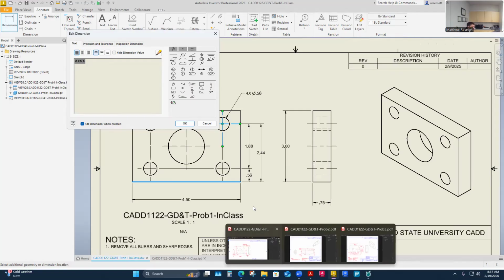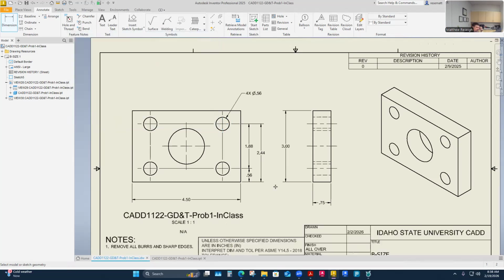And the more features you chain dimension with a plus minus kind of tolerance, technically you may get a position that is not correct because all these tolerances have stacked up, and now that feature of size is way off course. But with basic dimensions, we're kind of overriding the tolerance that's applied on the sheet, essentially. And we're saying, no, don't apply tolerance to this at all. This is a theoretically exact size.